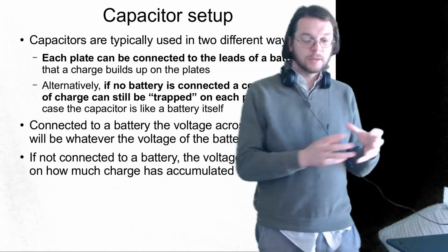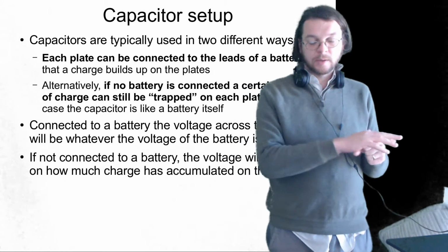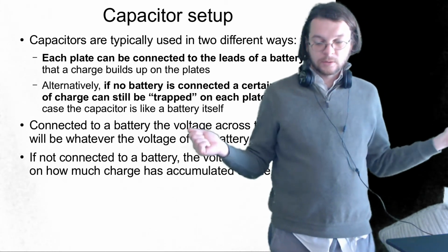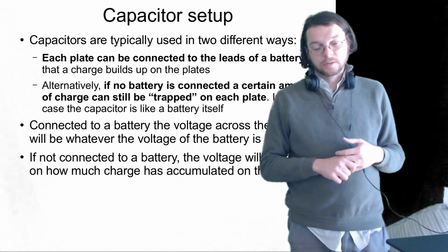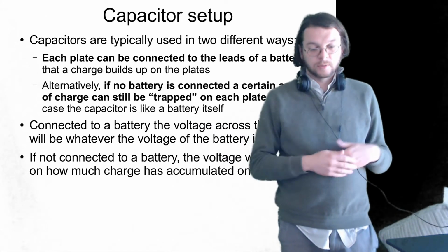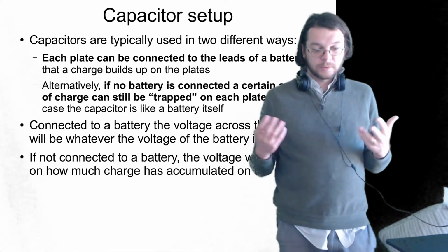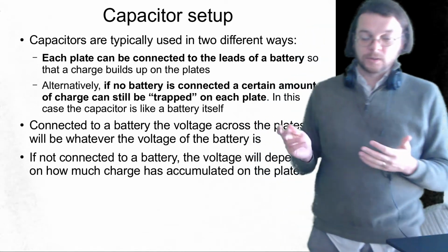and then I would disconnect it, making it clear that this thing is no longer connected to the battery, and then I would take a paper clip and put it on top of it and get it to spark, to prove that even though it wasn't connected to the power source, it still had charges trapped on the plates, an excess of negative charges on the one and a lack of negative charges on the other. And so it was able to hold that energy and that charge even though it wasn't connected to the battery.